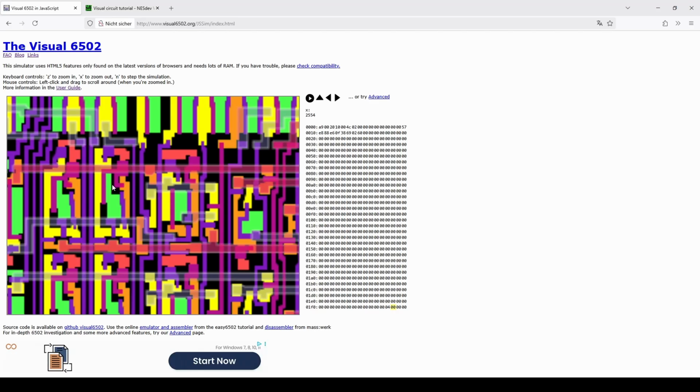And the cool thing about this is this basically combines the two functionalities into one. So more or less you could argue this is both acting as the pull-up, as the diode connected transistor to work as a pull-up resistor, but it's also actually controlling the inversion here, because this power here will then go through here, and because this is being powered by this section, that means that this area here can drain to ground, right?